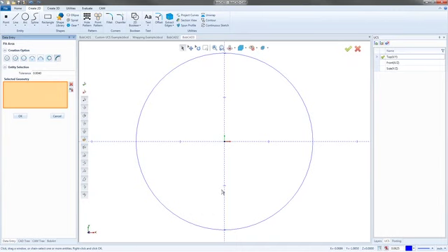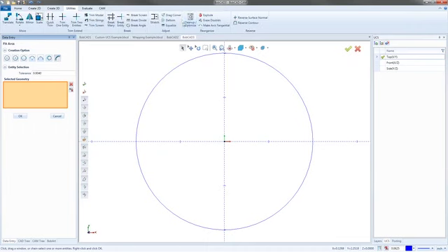The biggest problem people run into with this kind of stuff, I'd say, is people just don't realize that this fit arcs option is even here. So what people end up trying to do to fix it is they go to the utilities and start running this cleanup and optimize. Cleanup and optimize does not redraw arcs. It doesn't fix arcs.